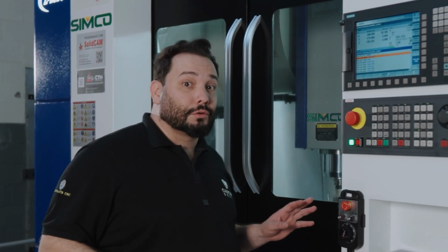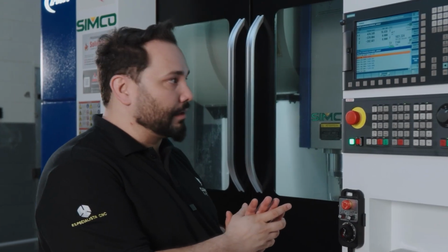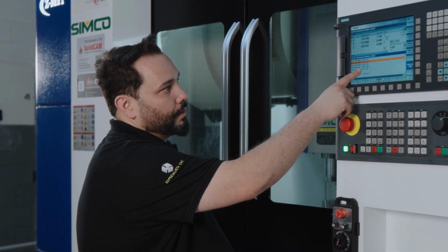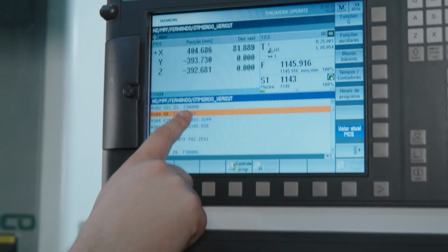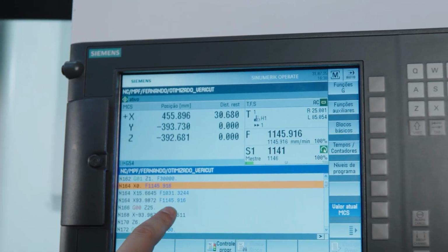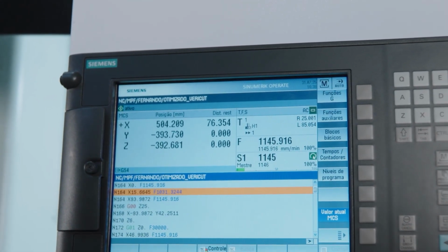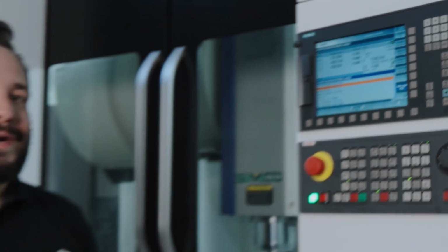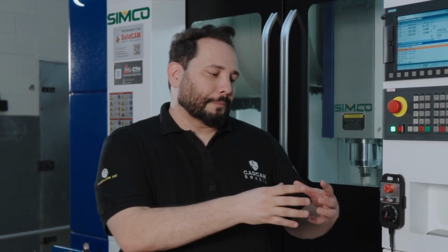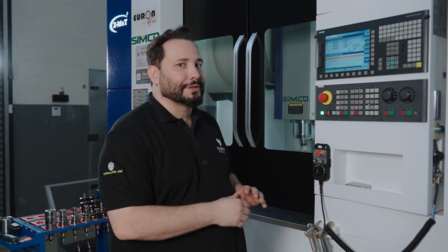I'm already noticing the first change here in the facing operation. When do I come here? In the program, several feed rate lines were added here, and the feed rates are quite varied. So I have the feed rate increasing, then decreasing. All of this is happening during the facing process. But I'm curious to see what happens during the contouring process. Because there, it's very clear that more material is removed at some points and less at others. Let's wait and see how this process turns out.